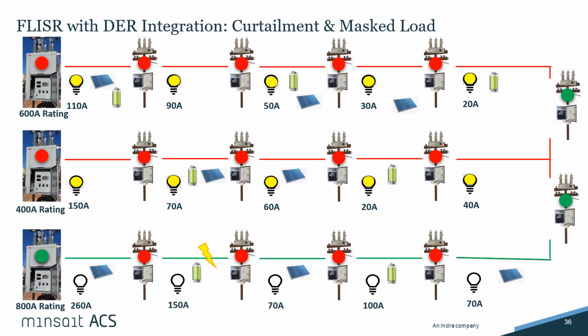And when there's a de-energized line, we also want to make sure that there is no backfeeding on that de-energized line. So that is the first thing that can be incorporated into the FLISR system, is simply that reassurance that those devices are not feeding a de-energized line. So from there, we'll continue. We want to isolate the fault. So we have done that here. We've isolated it. And now we want to start looking at doing the rest of our restoration.